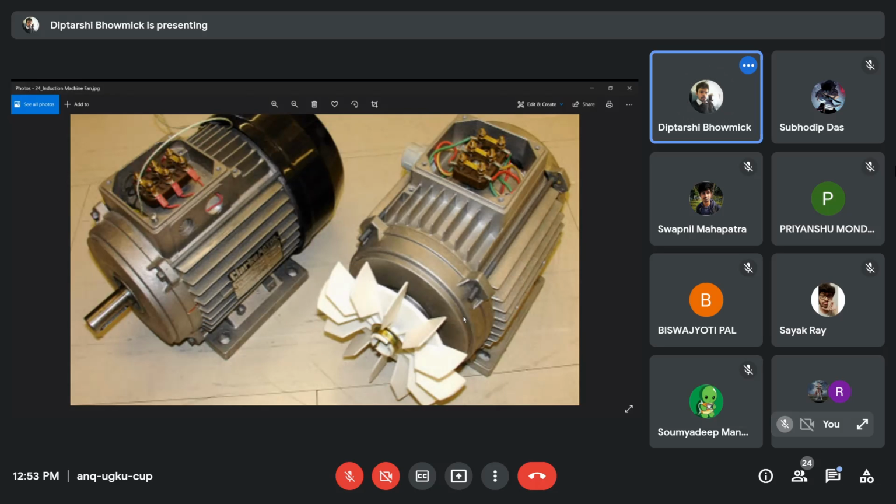So to eliminate that problem, we don't tilt the fan blades of any machine. We normally keep the fan blades straight, so that whether it rotates counterclockwise, clockwise, or any direction, the ventilation will not get affected. That means every direction of rotation will get the same ventilation. Clear? That's why the fan blades are parallel to each other and not tilted. They're flat plates.